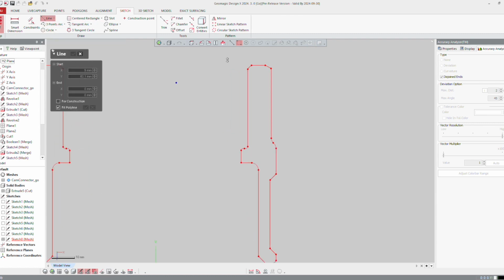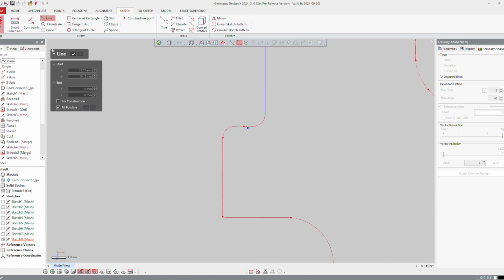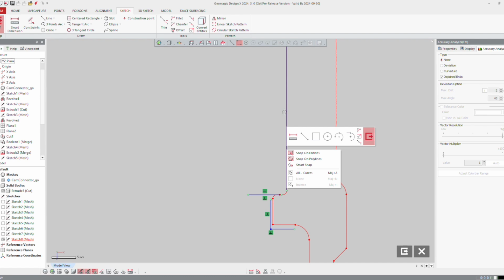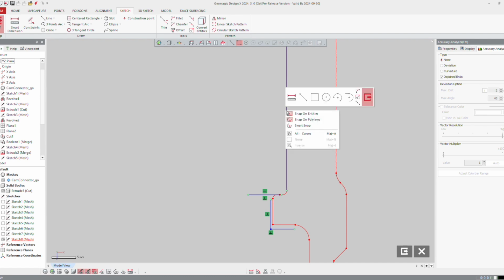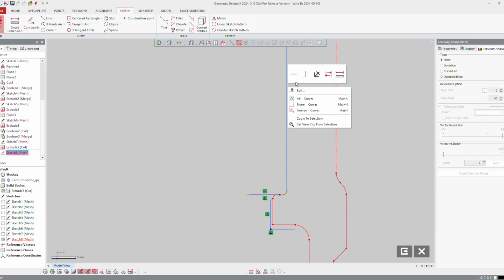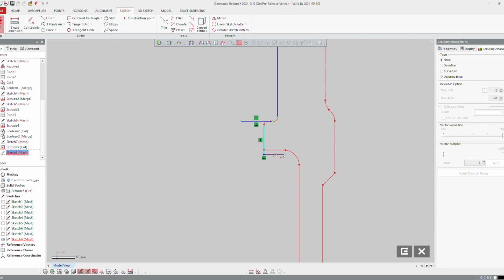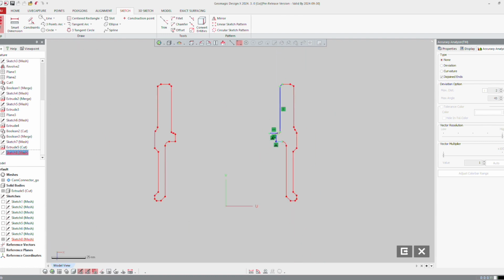So let's go line and create my curves. So that one is not right. I will take one point and move it out to get horizontality. And again, you can create by double clicking or by just clicking like that to define horizontality and verticality. And otherwise, you have to do it afterwards, like right mouse click on the line and verticality. This one got angle. And if you do it for outside, you need to remagnet the curve.